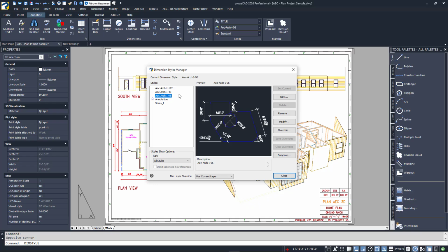So, the one labeled 96 is for 1/8 inch equals 1 foot views. The 48 is for 1/4 inch equals a foot views. It's probably easiest to do a quick internet search for these, but the formula is to invert the fraction. In the first case, 1/8 becomes 8/1, or just 8, and multiply it by the 12. That gives us 96. Longtime CAD users can usually just glance at the number and know what the corresponding scale is.